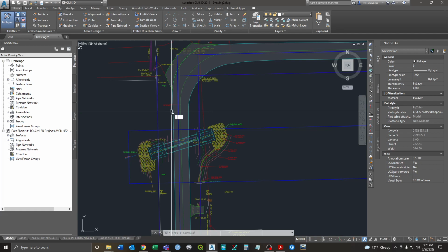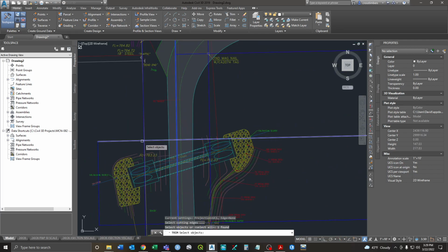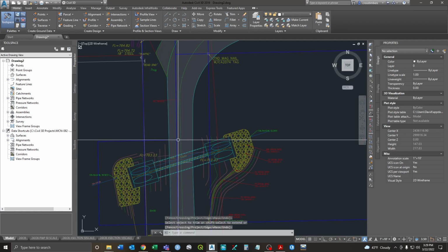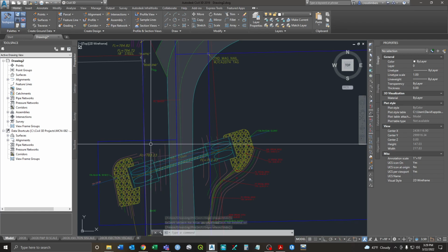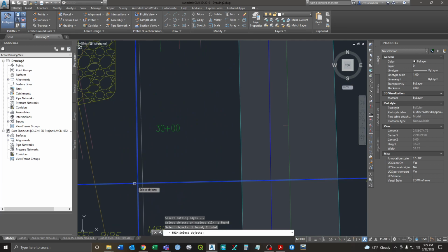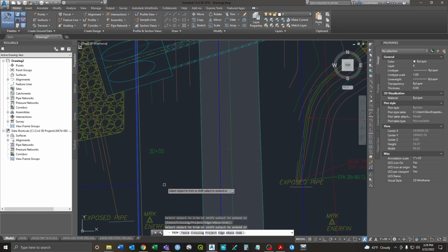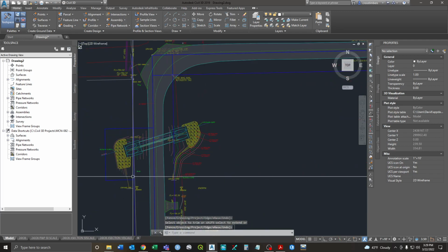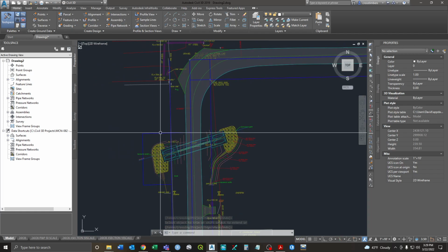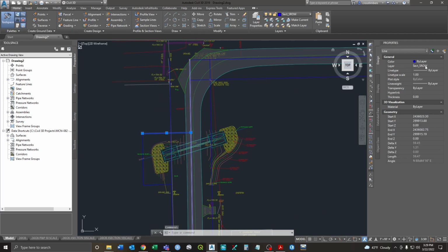So what we actually want to do when we trim this side, we want to pick the middle section line, and then the closest one to it, we're just going to trim it to there, because we actually need this to be part of our measurements, this little section plus this. Whereas the back side, we just want to trim it all the way to the statutory right-of-way line. Okay, so this is going to be the right-of-way we choose. So again, when we copied over this, we just kept it on this same section as statutory right-of-way line.